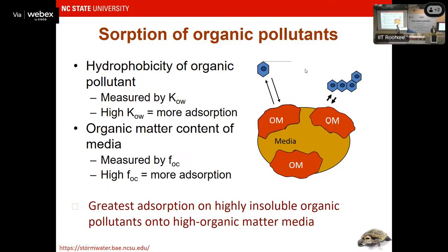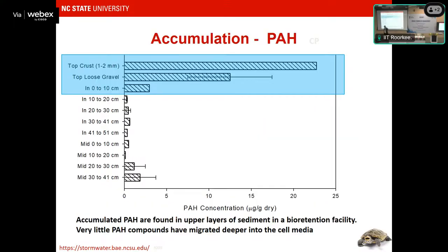Based stormwater control measure, as the runoff comes in, it's trapping the clays, the silts, the sands. But you know what else is trapping? Organic particles. Kind of cool, right? And guess what then attaches themselves to the organic particles that the stormwater control measure just trapped? Oils and greases. So it's literally removing one pollutant.